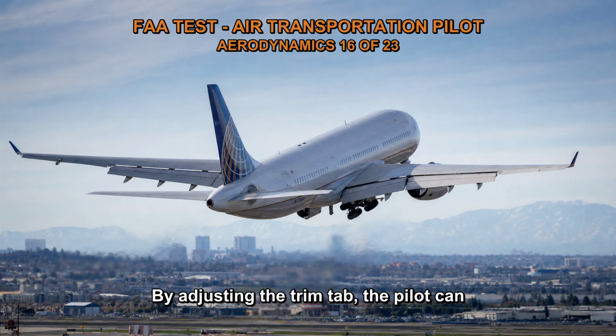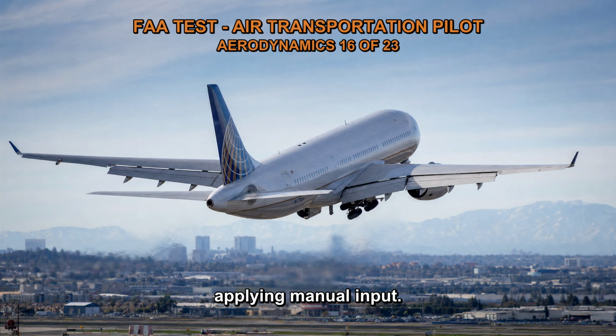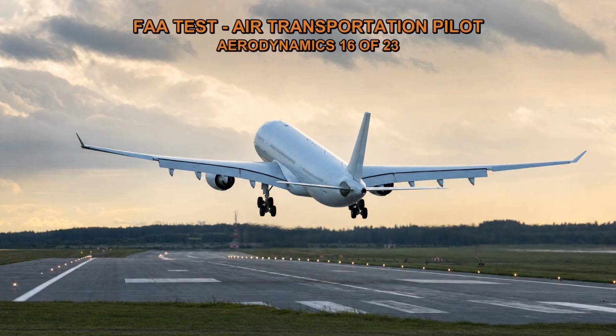By adjusting the trim tab, the pilot can set a desired position that helps to maintain the desired attitude or control forces without constantly applying manual input. Once the trim tab is set, it remains fixed in that position regardless of the movement of the primary control surface. This allows the aircraft to maintain the desired trim setting throughout the flight.